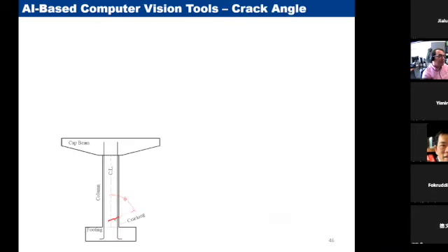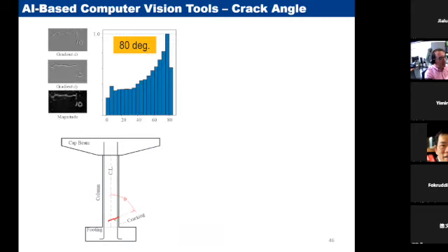What we noticed soon is that overall, a crack is a noisy animal. The crack in concrete goes around large aggregates. You do not have control over the way that it will propagate, but overall, as a human, you can recognize a general angle for the crack.